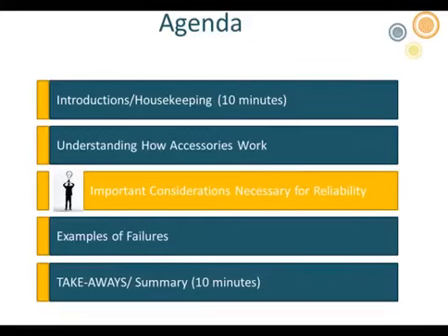If you take a cold shrink joint, it can vary as much as 1.5 inches in install length from the min to the max size conductor, just because of the laws of physics, because it's expanded significantly more. You will not get that big of a length change in a push-on because you don't expand it that much. So again, it depends on the type of accessory and the manufacturer. Hopefully that helps. Thanks.